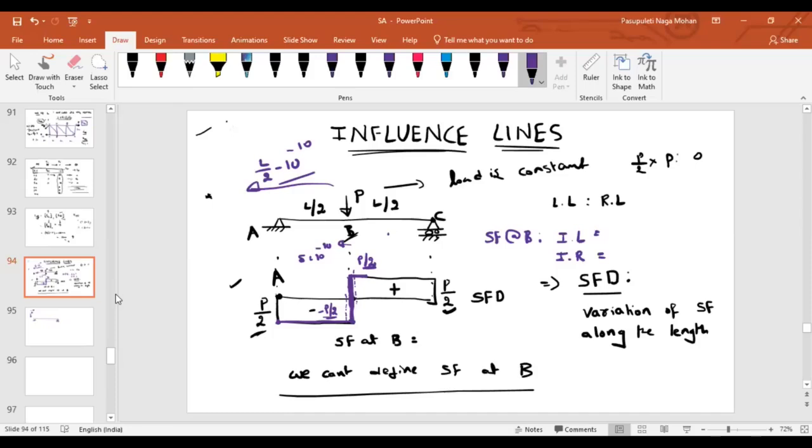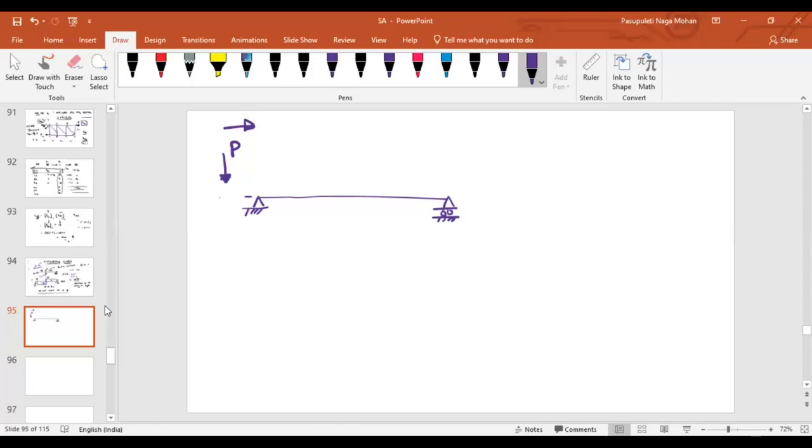Even in the design perspective, if you talk about the live load, whatever the extra load, even that we will take as a constant position. But if you're talking about bridges, or some crossovers, whatever it may be, then as the vehicles move, obviously the loads will change position from point to point, isn't it? So if the loads are changing position, then obviously the reactions or internal forces like shear force, bending moment, axial force, anything, won't be constant.